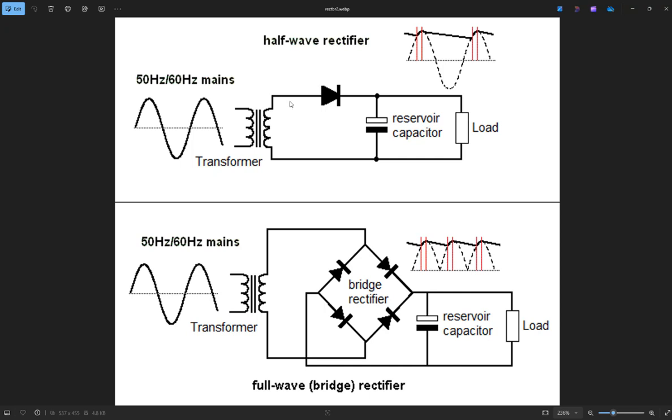Okay, this happens everywhere. Little adapter, the little charger for the phone. You see the little charger for the phone, right? Everyone has it. So that little plug, even though it's very small, if you open it up, you can see little transformers inside. So it's converting that 110 volts AC to a lower AC voltage and then rectifies it. So it has rectifier in it, has transformers in it, and eventually has voltage regulators, which means the rectifier output is probably giving, for example, 9 volts DC, and you use the voltage regulator to regulate it to 5 volts, which is providing the 5 volts power supply to the USB. Okay, that's how that works. It happens everywhere. Everybody should know this, okay?